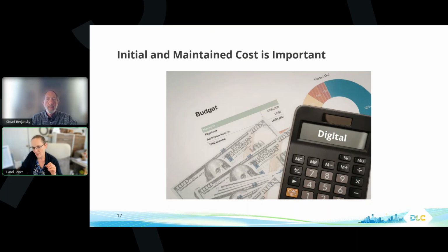And you can have at the same time with the DALI system a perimeter daylight zone, which is required by code most of the time, and you can tell that group to handle daylighting dim as necessary. But you also can have a different group for a different purpose that includes some of those daylighting fixtures. So it's not like you've got a circuit and then you're dealing with the fixtures that are on that circuit, and that's all you can do. You can map to the different fixtures and drivers and tell them what to do without changing the wiring. So there's tremendous flexibility. That helps a lot during the operational phase.